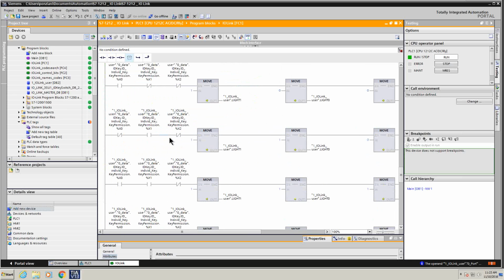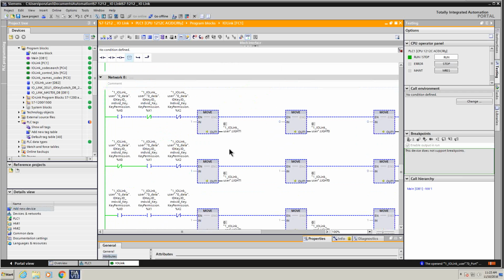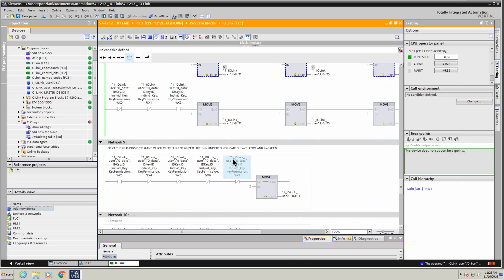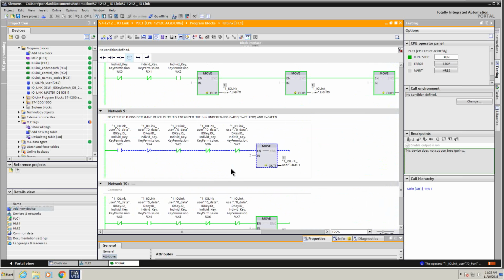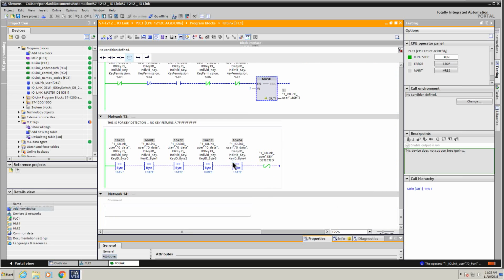What I'm doing with the code on the key switch is basically a comparison to see which key is in here somewhere. Here's where I'm doing my comparison. It's looking at the different values for each of my key switch positions. This particular key, without going into a lot of detail, has a code of 3F, 0E, BF, 17 and 04. These are all hex numbers.